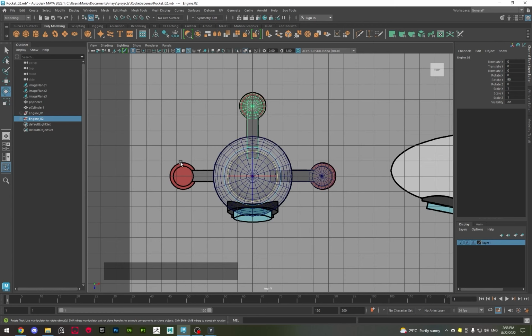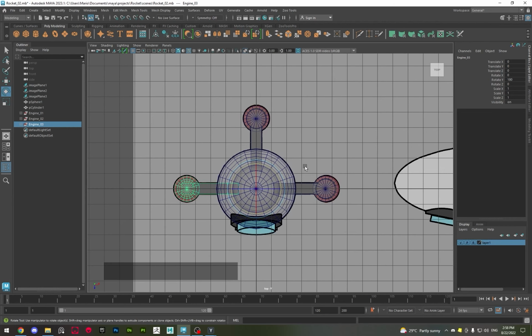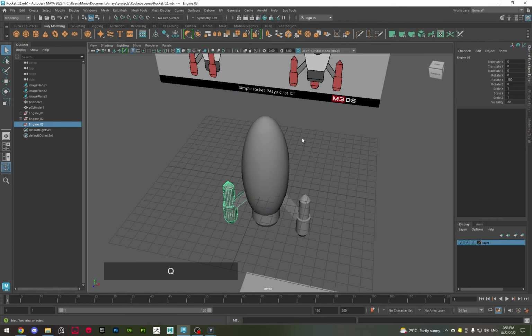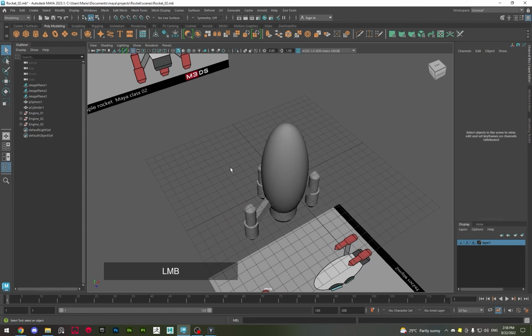And if I press Shift D again for another duplicate, it's gonna mimic it and move on once again 90 degrees. And if we press Shift D one more time, it's going to create another one, and it's going to move here for another 90 degrees. It just remembers the transformations that we made. We don't want this one here, so I'm going to just go back. Remember, when we do this, we can make as many as we want, but we can't make any other movements in between or any other clicks.